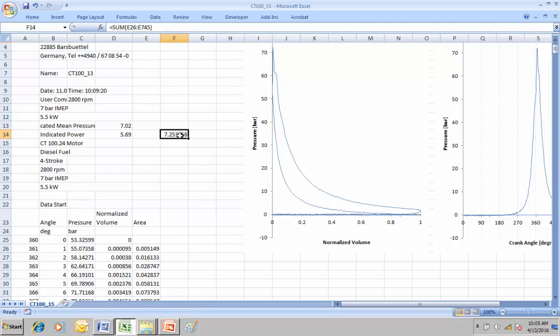So what I have here is the average pressure that's taking place. If you recall from mean effective pressure, mean meaning average. That's really what we're talking about. And so this is going to be measured in bar right here. And maybe I should have moved it up to the next line, because this is what the computer is saying. It's doing its own numerical integration of this system right here, and this is our numerical integration. You could see that they're pretty close to each other.